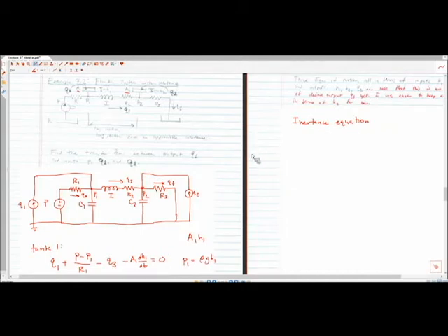So we have this pressure drop P1 to P2. If I were to express this pressure loss P1 minus P2, I can use Kirchhoff's voltage law, which is the pressure drop across an inductor. So the pressure drop across an inductor is equal to the inertance times the current through the inductor, or change of current with time of the inductor. And then I have the pressure drop across the resistor, R2, which is given by Ohm's law. All right, so now I have this relationship between P1 and P2, given this inertance.